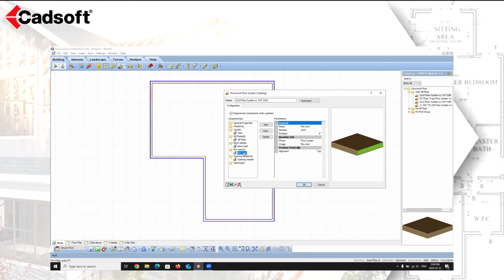Fan joist and rim joist, again, are going to be your rim joist materials. And then we also have opening headers, where you can have that defined as a header. And again, you can choose the type. All 3 of these will typically be the same size as the joists, but in some cases, like in an engineered floor, you may want to use an LVL for these pieces, while the joist will be an I joist. So in some cases, you will have different materials in these areas.